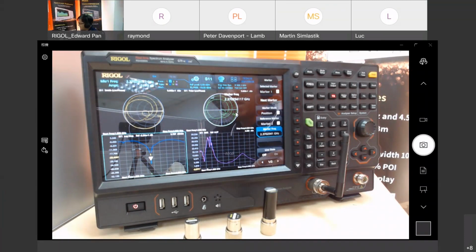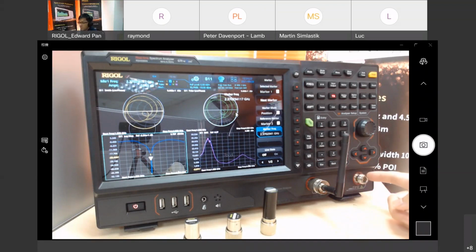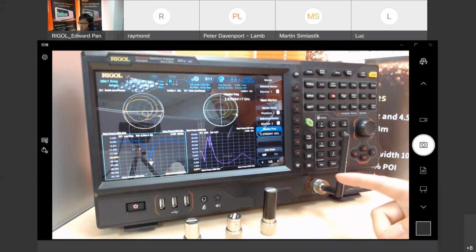Yeah, so you can see the front end side here. Here is the tracking generator of the spectrum analyzer, and the right-hand side is the receiver of the network analyzer. It transmits the signal to the device and gets the signal back through the directional coupler inside to the receiver side of the spectrum analyzer. So we can do the final result calculation by the mathematical formula. Yeah, it is very simple.